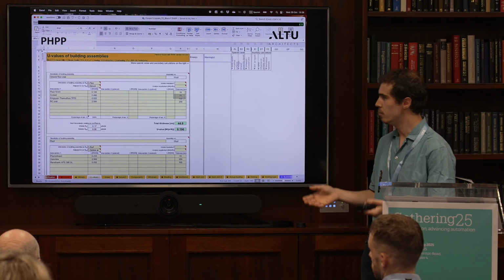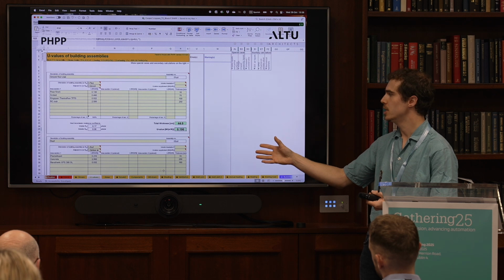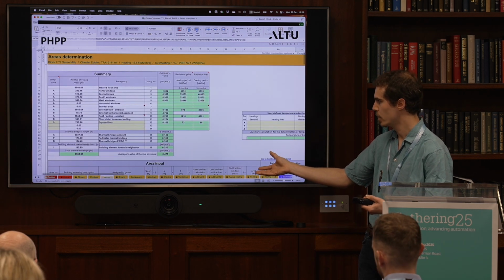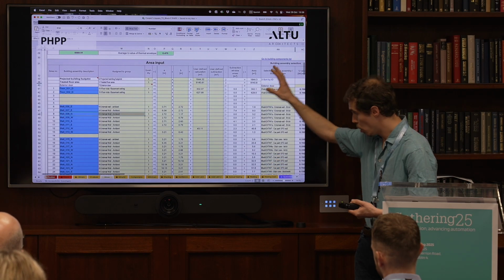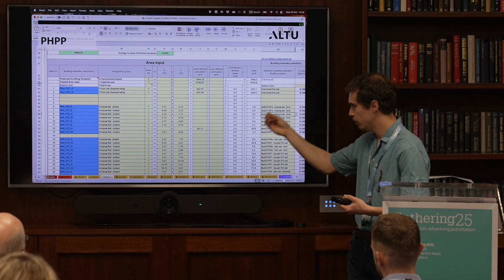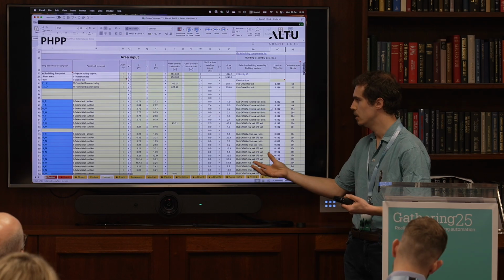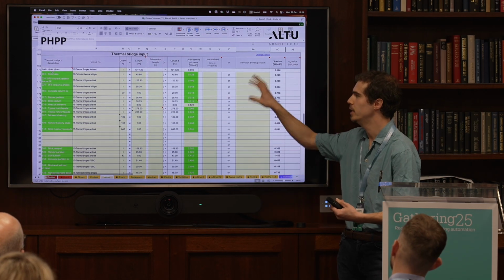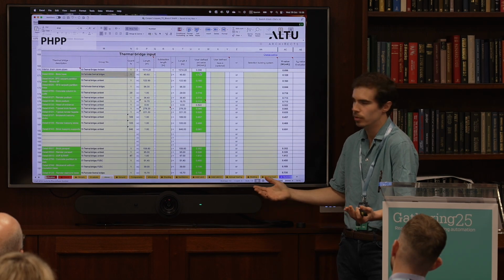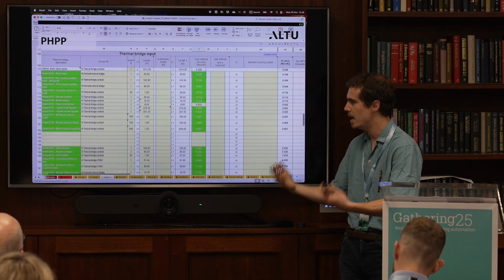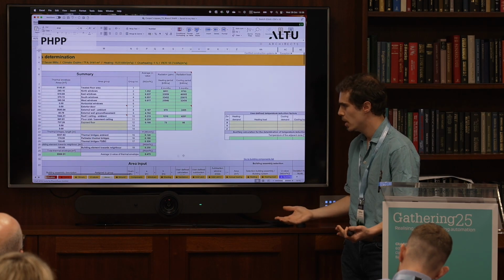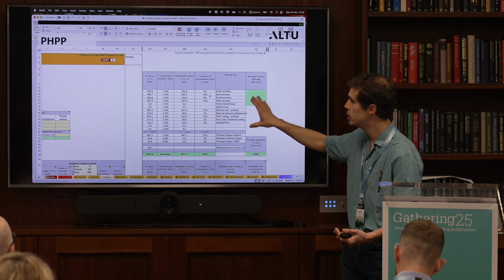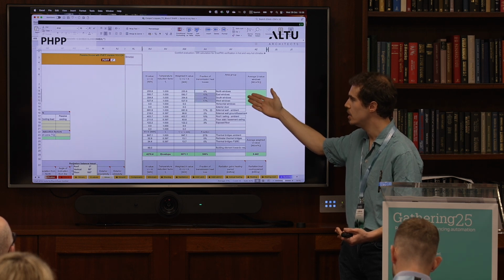So for that, we've got all the information of our assemblies, so the U values of each of our thermal envelope components, all of the areas. So you can see all of this information is coming automatically from our SketchUp model. We haven't had to input that individually, which for this scale of buildings would be basically impossible. But it's all in here, along with the thermal bridges, and now we are able to tell how much heat is escaping through each of these elements.